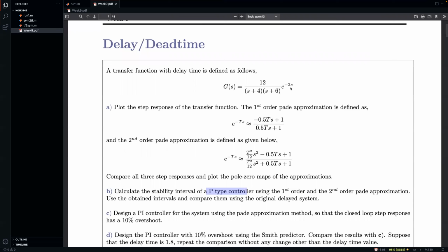So we can conclude that the system with delay has infinite amount of poles and zeros. Therefore, it's not possible to, for example, plot a root locus plot because it doesn't have finite amount of poles and zeros. The first step of a root locus plot is to place the poles and zeros of the system. But if there are infinite amount of them, how can I place them? And the best thing, again, the closest thing that we can do is just use the Padé approximation.